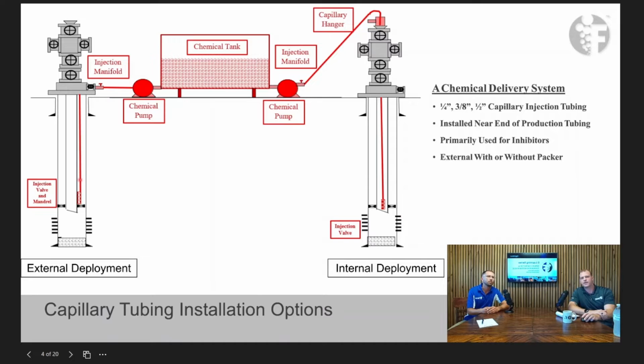Correct. So how do you typically attach that to the run tubing? Usually outside of the tubing you'll run some clamps, depending on the deviation of the well. If it's over 10 degrees is the rule of thumb. Okay. So you're looking at the inclination of the well to decide that. Correct. So if it's over 10 degrees, definitely run clamps.